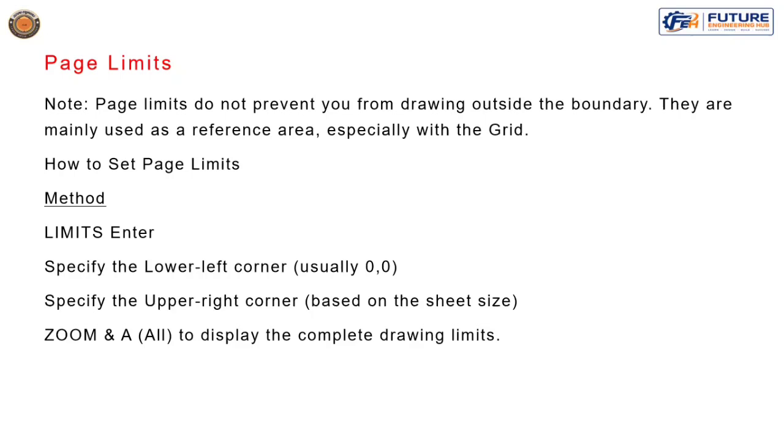Then the zoom command: Z enter, zoom all, A enter, to display the complete drawing limit.